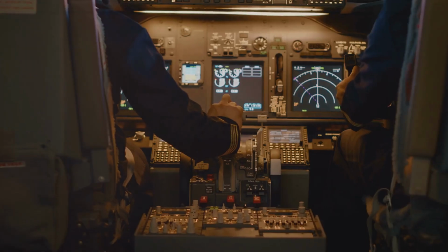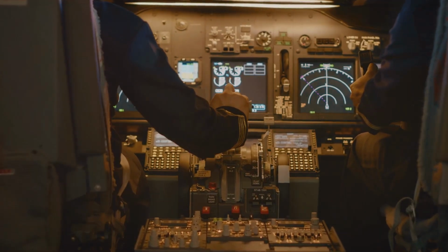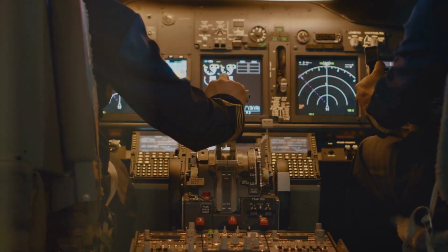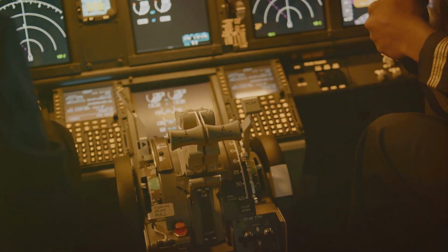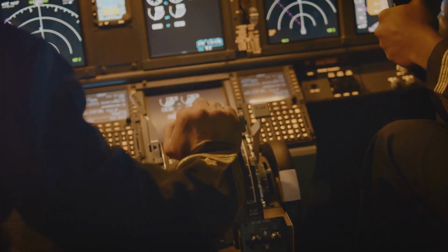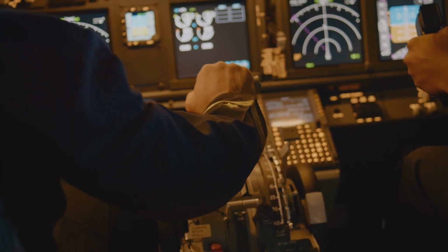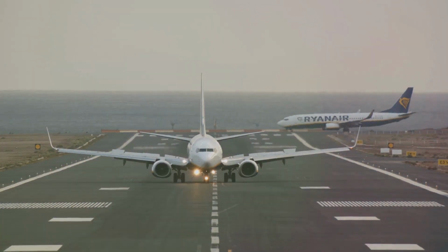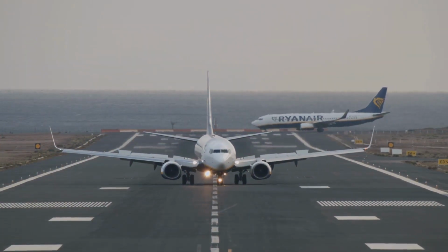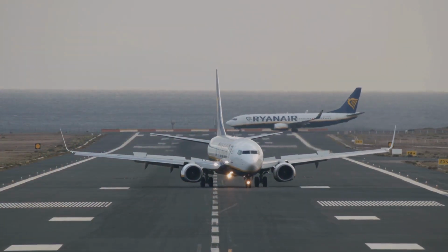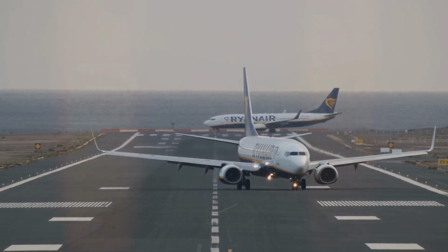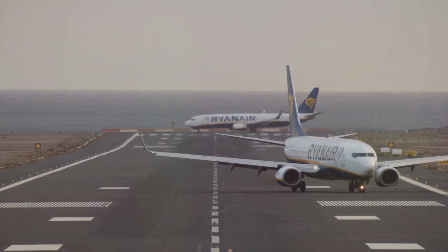Then there's VS1, the stalling speed or minimum steady flight speed, at which an airplane is controllable with its wings level and landing gear retracted. It's a crucial speed to be aware of, especially during takeoff and landing. VS0, on the other hand, is the stalling speed or minimum steady flight speed when the landing gear is extended and the flaps are in landing position. It's another vital speed to consider during landing scenarios.